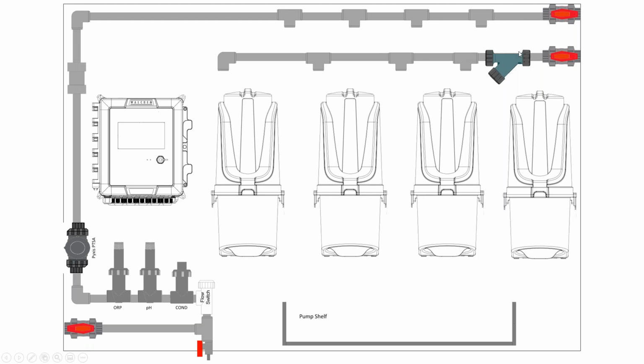But as you can see, the other side of the setup is we've got a pump shelf. You're going to put your pumps down here, and then you can take the tower loop, bring it in, past your sensors, past any sort of back check, bring it into injection points. So the lower leg points are feed water points. The upper leg we're injecting into the system. And this sort of setup is really nice, really professional looking. We can mount this on a frame, and on the underside of it, we can put a cabinetized system that lets you store your solid feed chemicals underneath in that area. Looks very professional. Of course, you have a locking cabinet to keep out the people who want to help themselves to stuff when they shouldn't. So it's a nice setup.